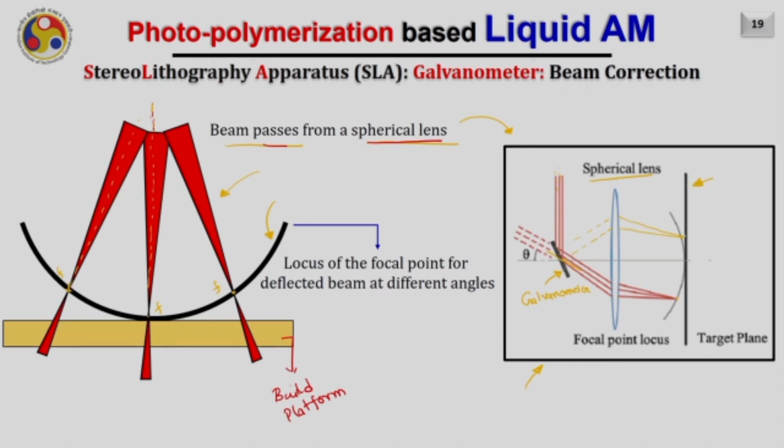Therefore what you will get on the target plate will have some different diameter, because you know that typically when a laser gets focused, for example this is a typical laser, this is the collimated beam, when it passes through a lens, it gets focused at a particular point and the laser beam typically travels like this. This is the minimal waist radius, also called the focal point.